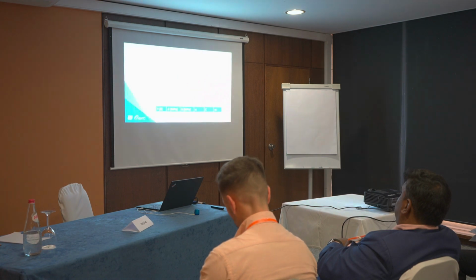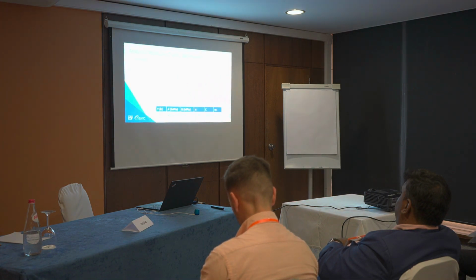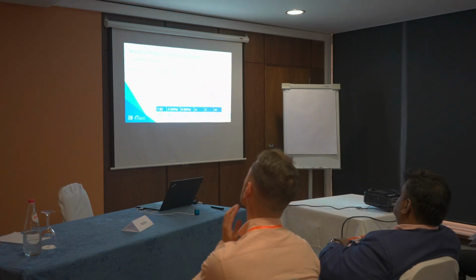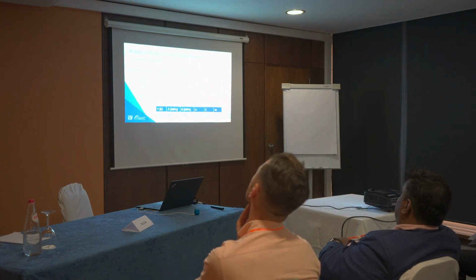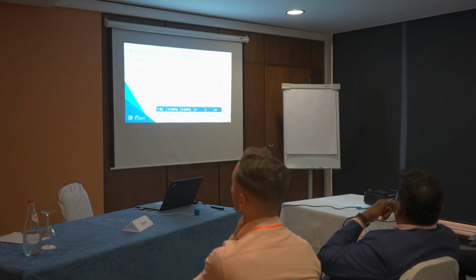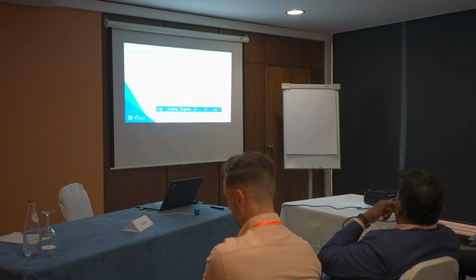We went ahead to utilize analytical models to model the plastic deformation, and we utilized 3 of these models. The first one we use is the Johnson-Cook model, whose equation is given here, for the flow stress. The constant parameters are determined from experiments using different approaches.